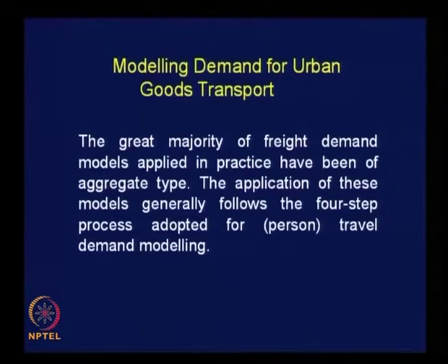The application of these models generally follows the 4-step process adopted for travel demand modeling. There is no variation as far as the different steps to be followed are concerned. We are going to do trip generation analysis, mode choice analysis, trip distribution analysis, and route assignment in respect of goods movement.